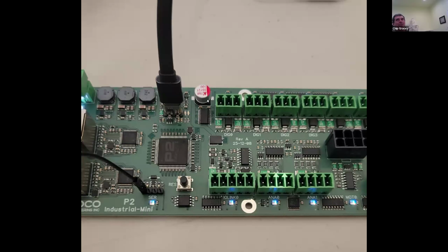So that chip is kind of dangerous to use on a circuit board because they'll have like a 24-volt supply input next to a 3-volt digital signal. So what I was doing is I would power the board down. I would put the probe onto those pins because I wanted to make sure that I was signaling the chip correctly, because it has its own SPI bus, right? It's talked to by the same cog that talks to the I/O expansion stuff and the LEDs. But anyway, it has its own pin. So I wanted to see that I was signaling it right.